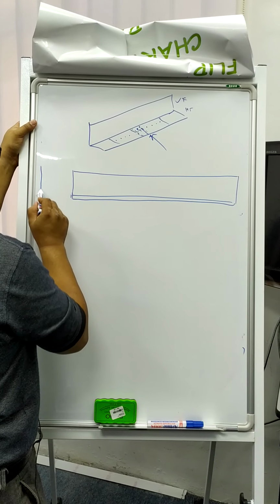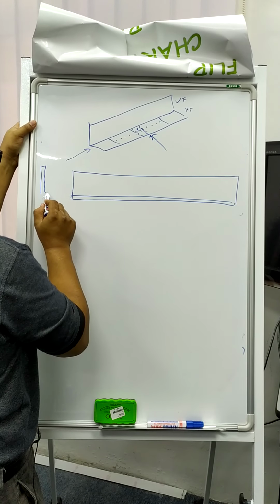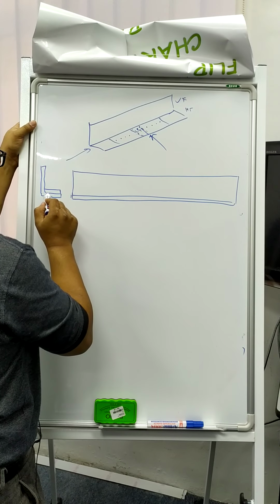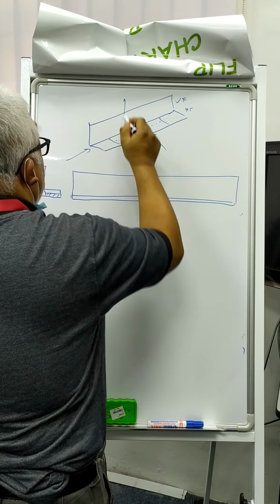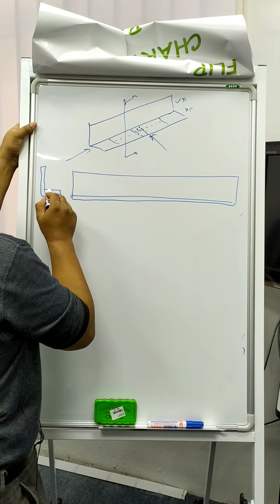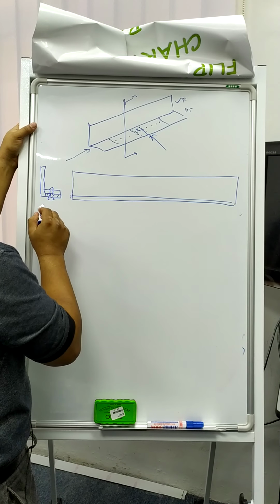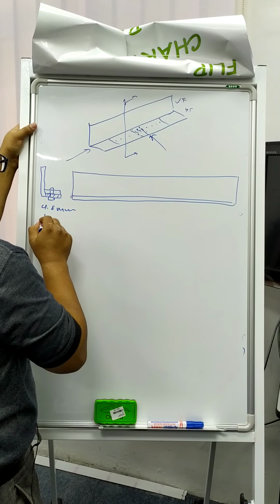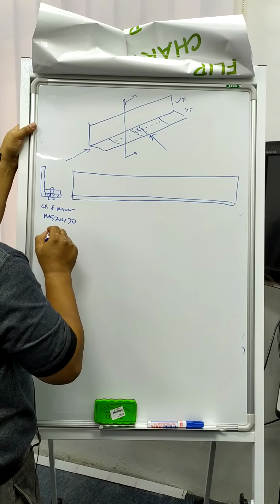And then if we look at the front side view, we have the doubler, and this is all the filler. If we cut through here, and we have installed 4.8 millimeter MS 20470 AD rivets.